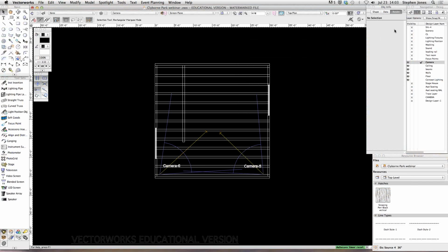The second part of the webinar today is about that very thing, which is how to take, from an entertainment standpoint, how to use the theatrical lighting library features that Vectorworks provides to figure out things such as photometrics and beam angles, how to create lighting plots, as well as how to generate all the paperwork that is useful to those that will be ordering, installing the fixtures, focusing, and doing all of those things.